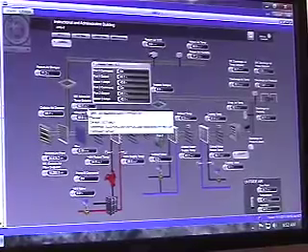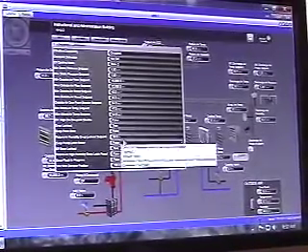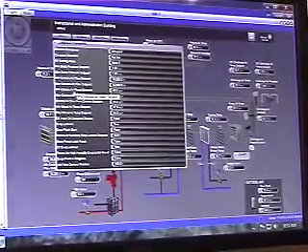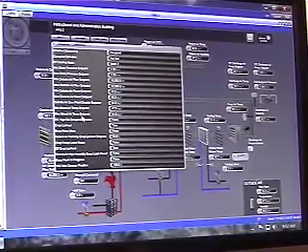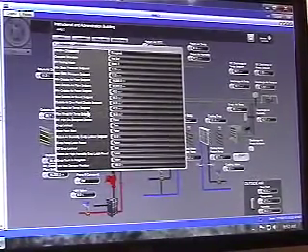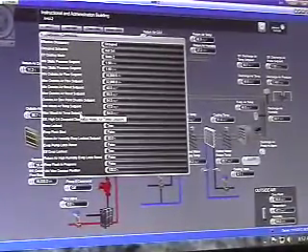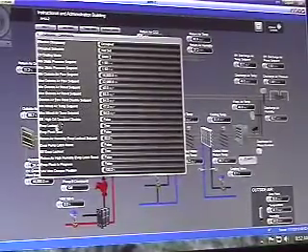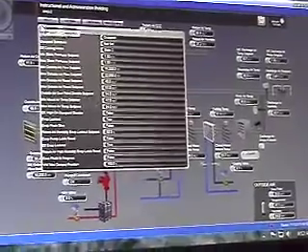This set point resets off outside air temperature. And you can see here, you have a minimum outside air reset of 40 and the max is 55. We'll reset your discharge air temperature between 47 degrees and 54 degrees. So on a really warm day, it'll be trying to maintain 47 degrees, and as it gets colder, it raises up your set point to 54 degrees.